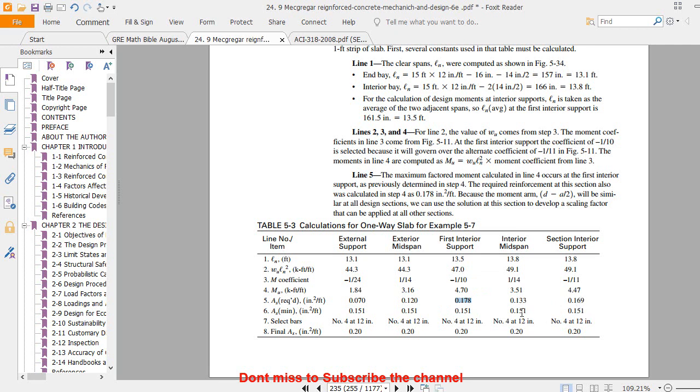This one is less than, so we are bound to use this value. Similarly, we are bound to use this one because it is greater than the minimum. Here we cannot use this one, we cannot use this one. We will use this minimum reinforcement. So for this 0.151, we select this amount of steel, number 4, at the rate of 12 inch center to center.